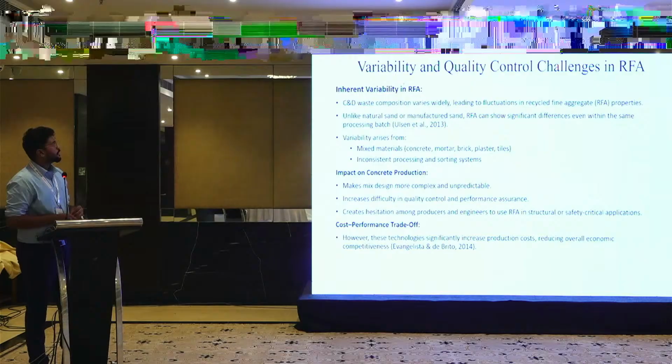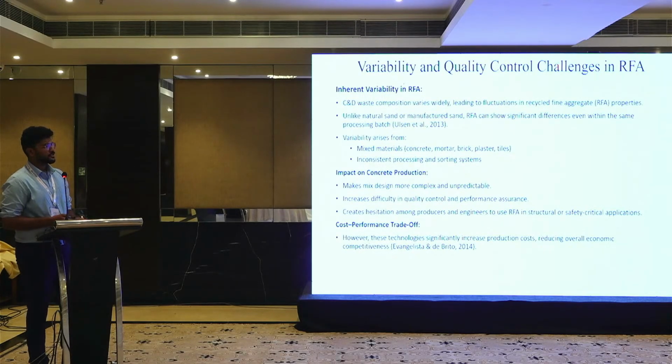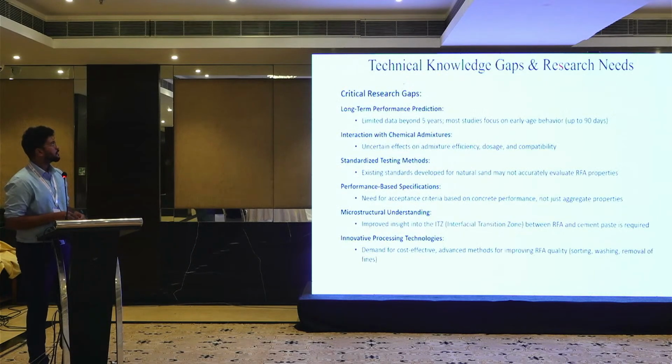Variability and control challenges in RFA. There is inherent variability in RFA. Variability arises from mixed materials and inconsistent processing and sorting methods, and makes mix design more complex and unpredictable. Increased difficulty in quality control and performance creates hesitation among producers and reduces willingness to use it in structural or safety-critical applications.